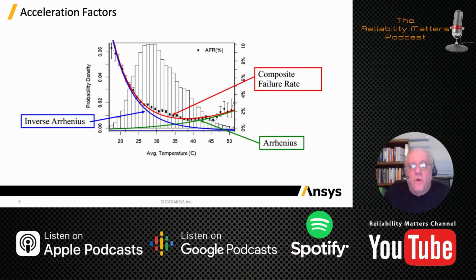So I talked earlier about acceleration factors and higher temperatures creating higher failure rates. For most materials, processes, and designs, that's true. There's an equation called the Arrhenius equation that we in the reliability world use to develop those acceleration factors from tests.